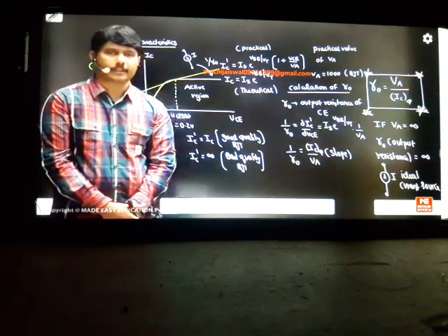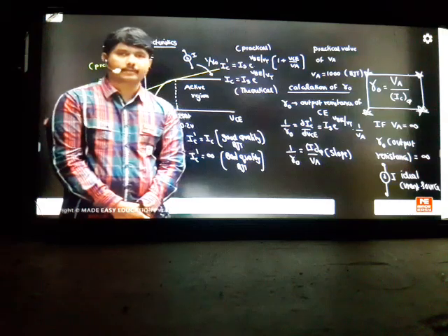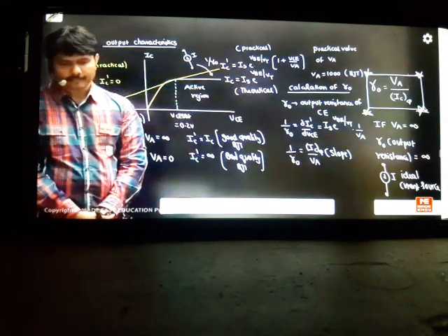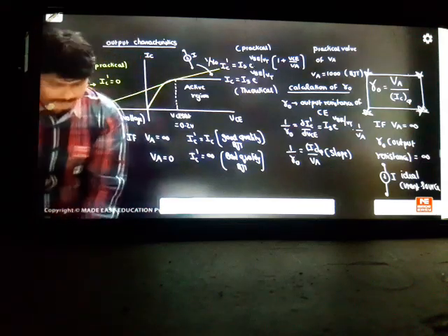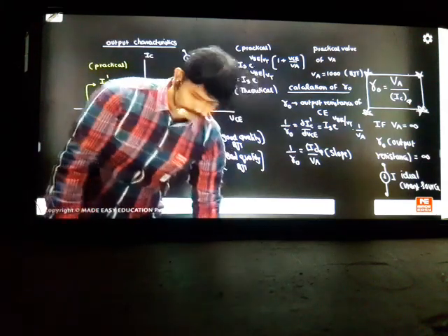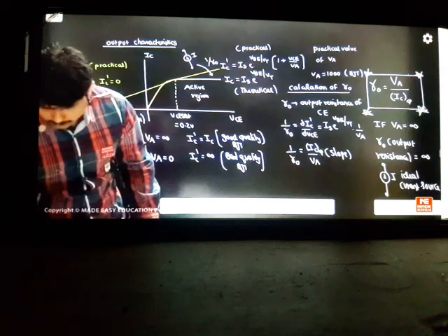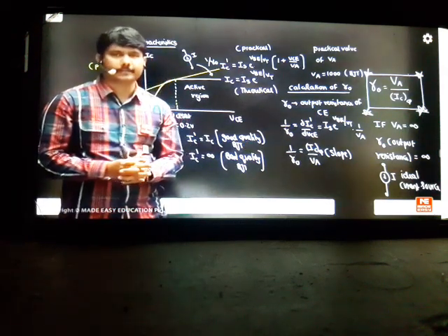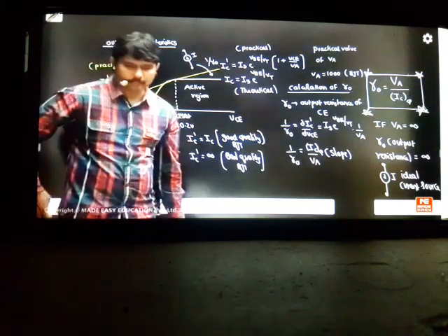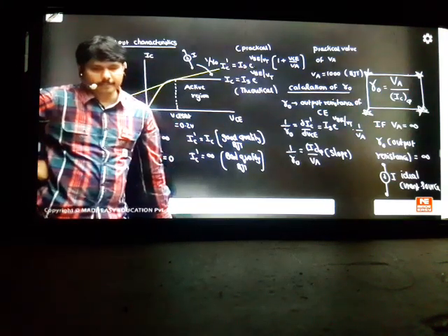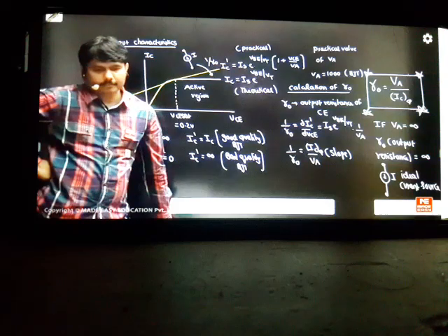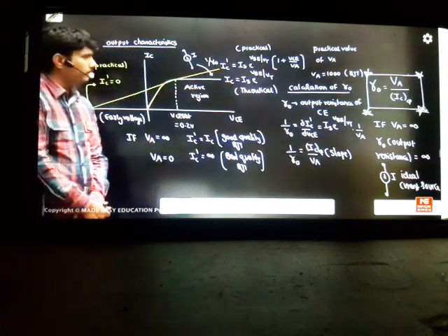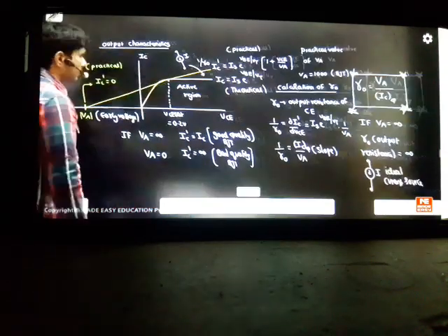Because for any transistor, MOSFET or BJT, this concept happens: in current saturation, the current will increase. There we have the channel effect, here we have the base width effect. Both will have the same impact. One is channel effect, one is base width effect. Yes, theoretical you can consider as ideal in the class. Theoretical and ideal will be the same in the class. Practical is different. So be clear about this concept. Yes, Anupam Das, we can consider the theoretical one as the ideal one in the class. So please cover the total board and nicely write down all these important points.